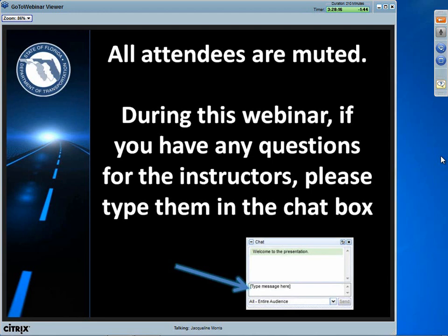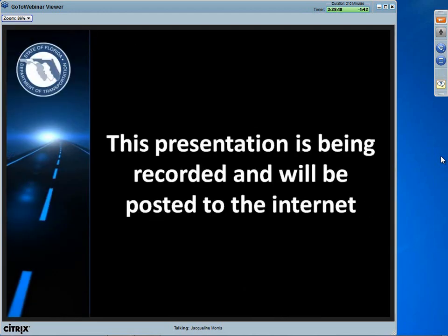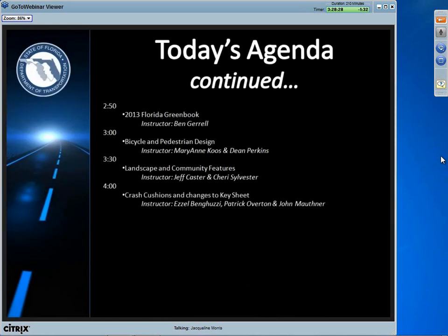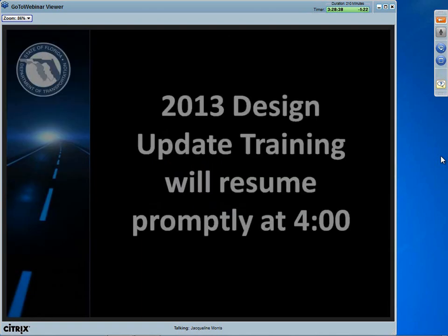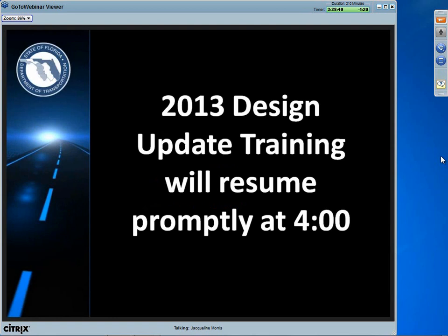So if we think back to that picture that I finally had a chance to show you, where we had the new special emphasis crosswalk that had been kind of pulled down the hill and was at a more level part in crossing Easy Street, that side street there, US 41 in Citrus County. And so what they've done is they've worked that crossing to be a little closer to the travel lane to get a shallower cross slope.